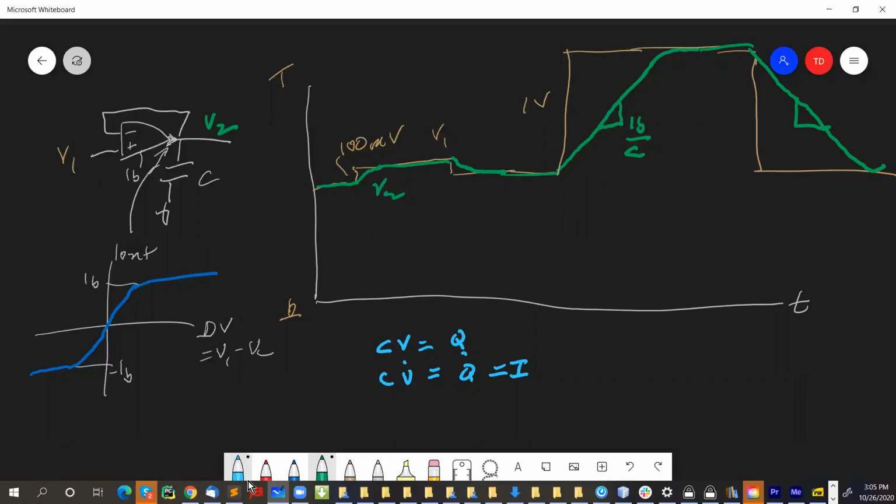What do you think? Instead of recovering from the step exponentially, it'll just recover like a line, and eventually it'll go exponentially out. And so what does that mean? That means that there is no definition for large signal. There's no definition of a cutoff frequency. It's really a different kind of thing. It's defined by the slew rate limit. The slew rate limit is just the bias current divided by the capacitance that you're driving. That defines the maximum rate of change of the output voltage with respect to time for the natural response of the system.